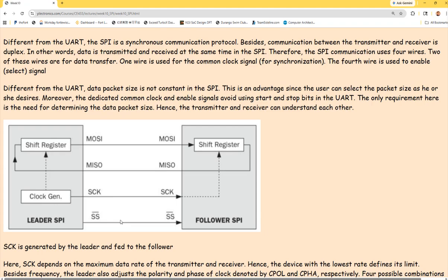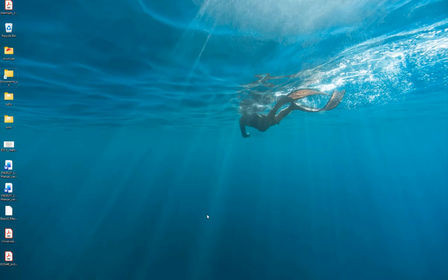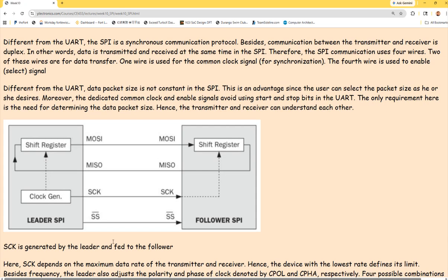Sometimes it's called CS, sometimes it's called SS. I didn't look into that. So the second one is a select. What the first S means, I didn't really pay attention to it. But usually it's using a CS. So when it's showing a CS, it's a chip select. That's what I usually see. But SS, I don't know, I forgot. But it doesn't matter. It's just a select pin. Just making a selection. It's active low.